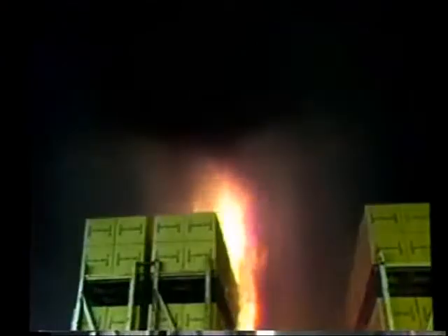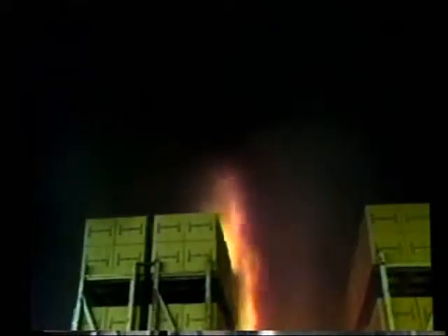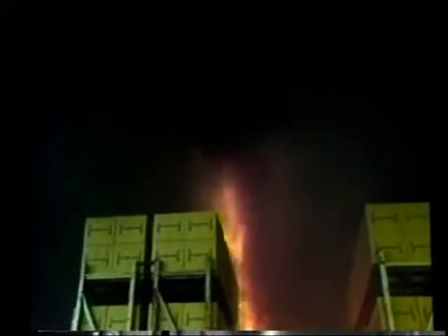Large drop sprinklers came about as a result of a study begun in 1968 by Factory Mutual on the performance of sprinkler sprays and water drop size. As the name implies, the sprinkler is designed to produce a heavy discharge of water droplets. Research showed that large drops, along with sufficient water pressure and adequate sprinkler distribution, were able to penetrate the strong updraft generated by a severe fire.